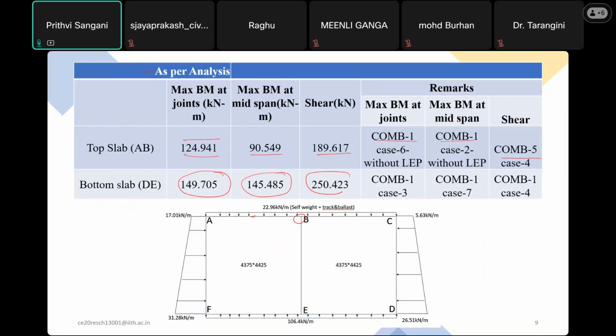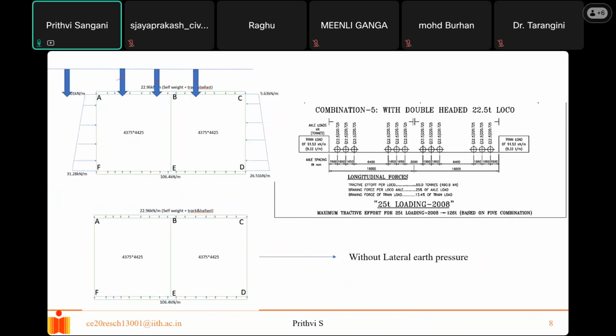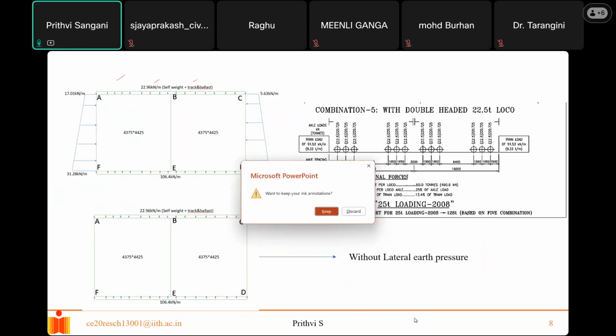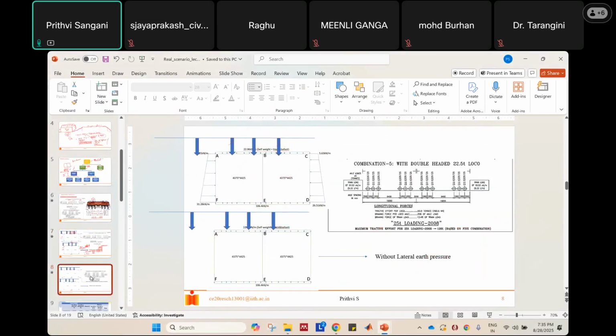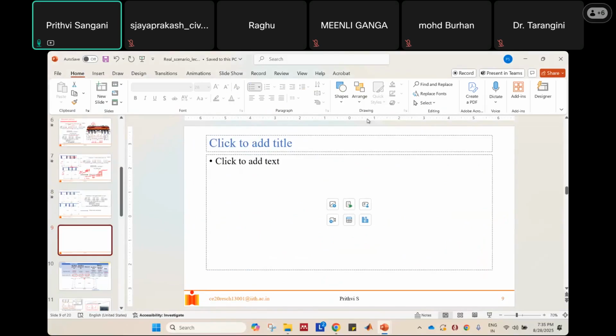And instead, I think you have this feature where you can run a train of loads. A train of loads can be run along your loading sections. So this is directly from STAAD. Instead, let me just show what I have done in STAAD. The STAAD analysis was very direct. I have simply created one box culvert.